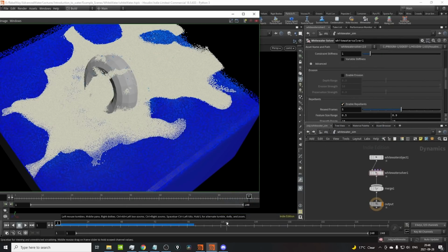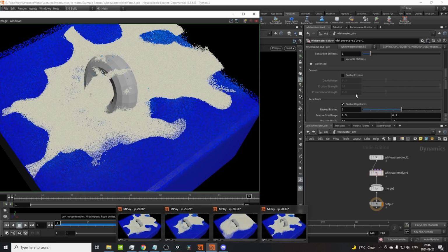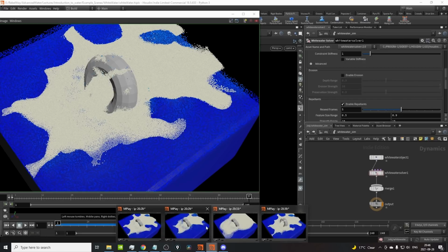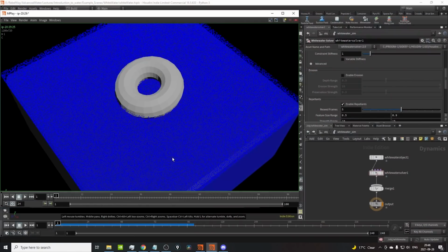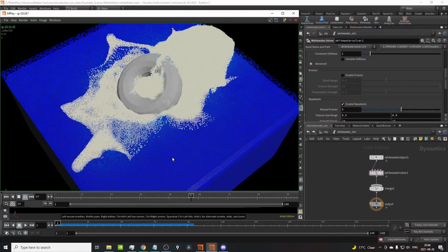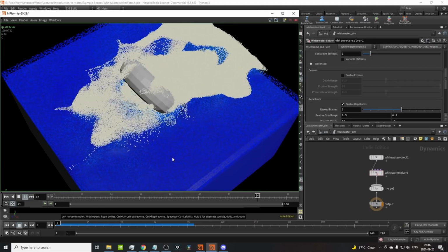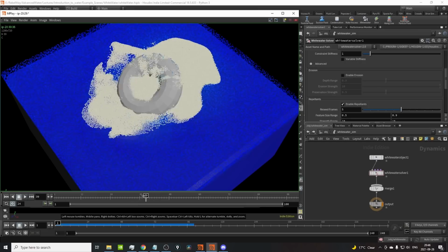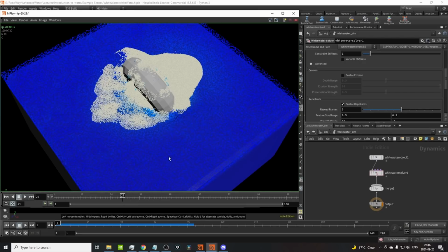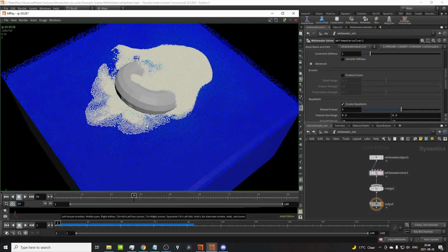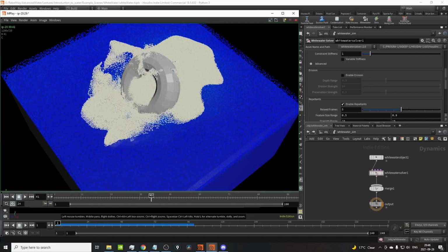So the way erosion works, it basically uses that density field that was generated at all times, of how many particles are active where, and uses that range of density to slowly kill off particles. So if we look at what this looks like with quite a heavy erosion setting, just so we see what happens, we can really see how this foam just dies off a lot quicker. And the reason is it's very low density areas here, right? It's high density, it's nice together, it's clumped, and now it becomes low density as these particles push further and further apart from each other, and now we're starting to kill those guys off.